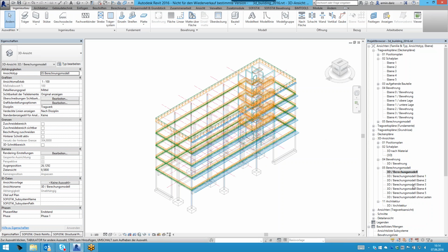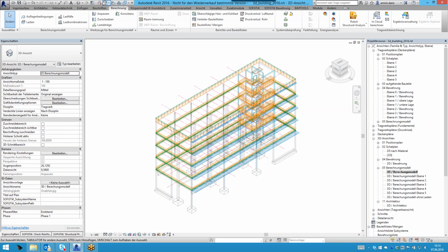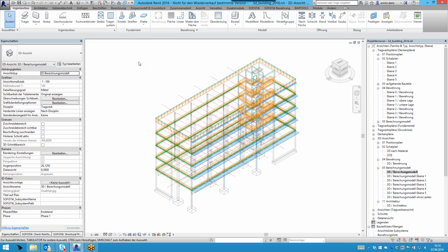As you can see here on the right-hand side, I have a view which is the analytical view of my Revit model, where some adjustments are already done regarding the analytical model. Therefore, we have some possibilities inside of the Revit platform technology. We also have possibilities to apply some loads with different load cases. This is all done in the Analysis tab of Revit itself. You can also define some support conditions if you like and create your load cases. This is all platform technology.